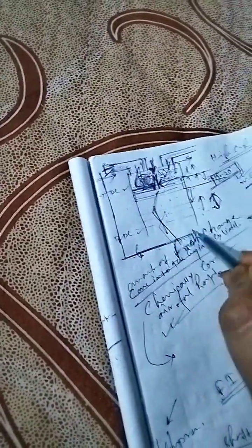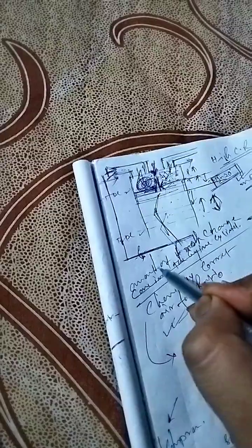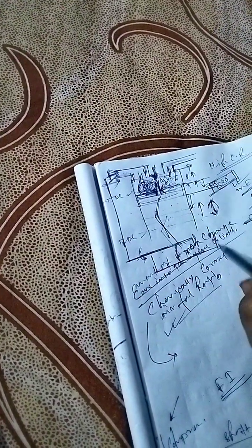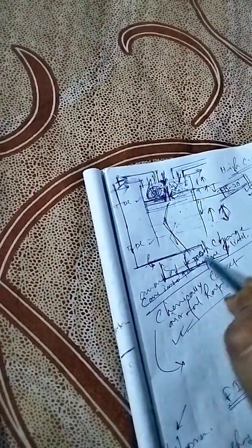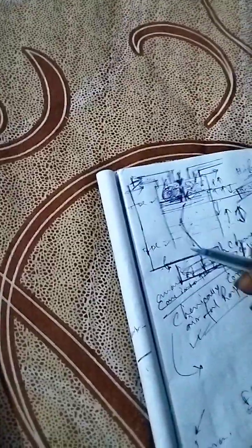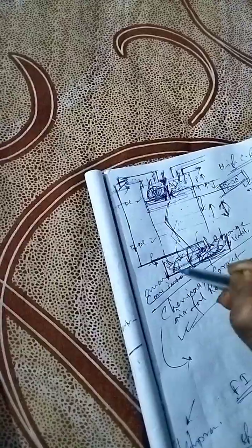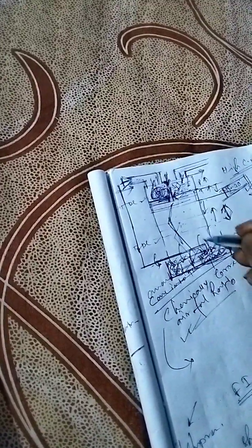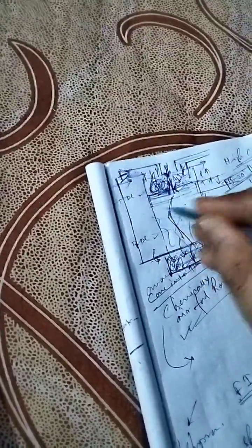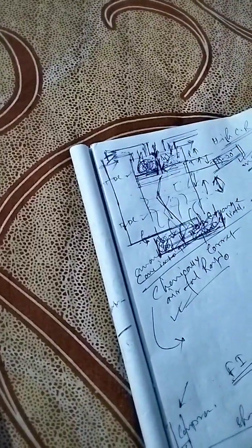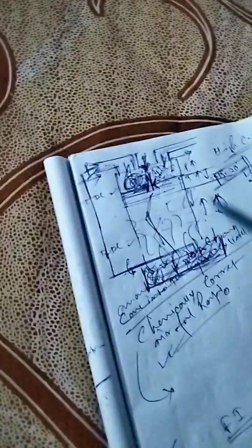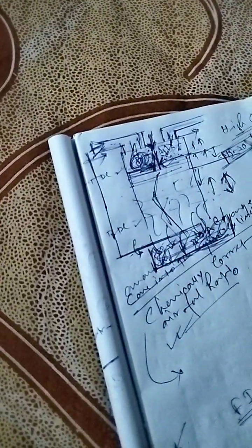And the lubricating oil, how do we place the lubricating oil? This is the crankshaft, and this is the bottom of the crank. We place the sump with the lubricating oil here. With every revolution of the crankshaft, it strikes the lubricating oil, and the lubricating oil spreads to the internal part of the engine cylinder. So this is how the lubrication is done. This lubricating system is known as the splash lubricating system.